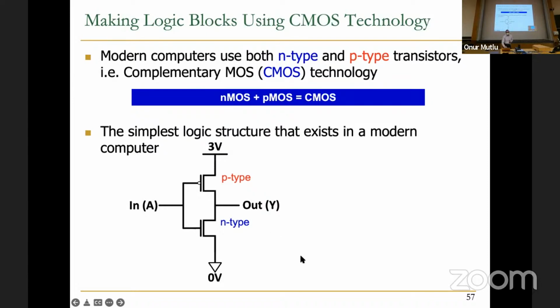So if I ask you, what does the circuit do? What would your answer be? I have one. It's a NOT gate. Does anybody know what a NOT gate is? Yes, in the back. Exactly. It's an inverter, basically. It's a gate that inverts the input. What does this mean? If the input value is 0, you get a high voltage at the end. If the input value is high voltage, you get low voltage or 0 voltage at the end.